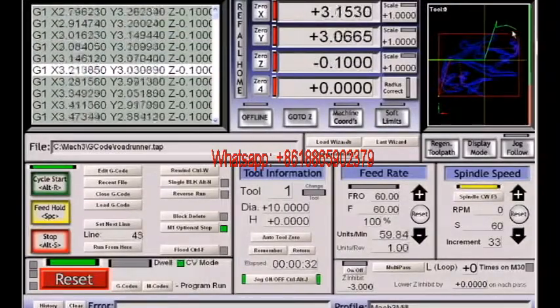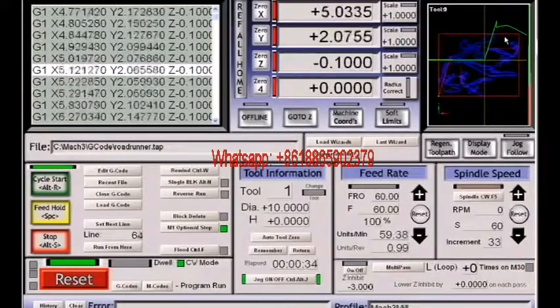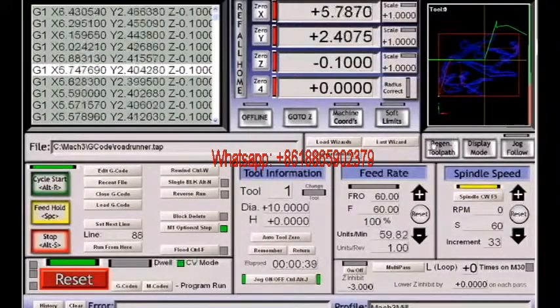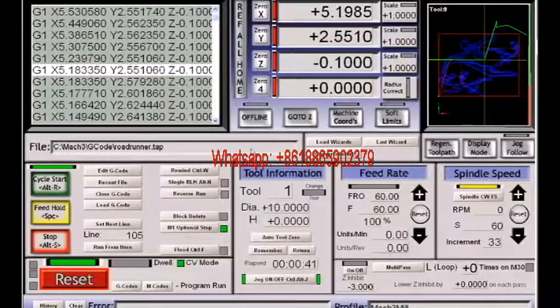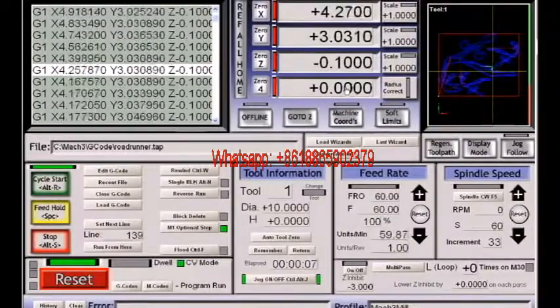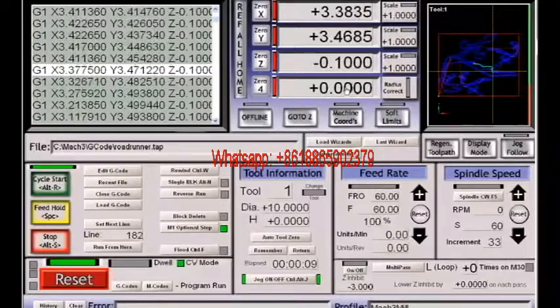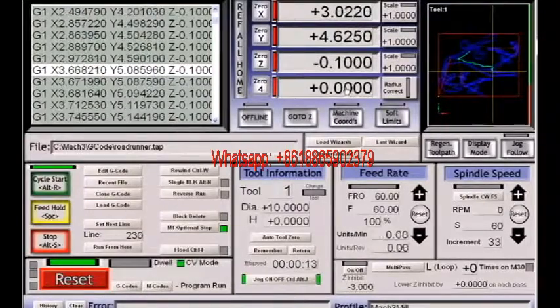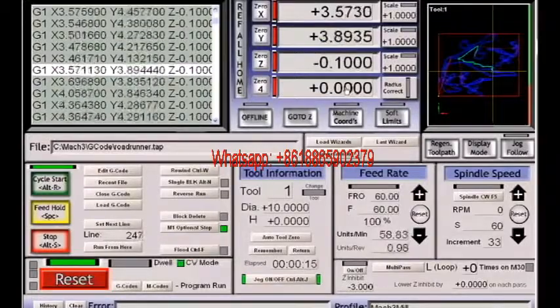Now you notice it's cutting in the wrong place. That's because we did not regen the toolpath after all our playing here and zeroing. So it's important, I'm going to stop this again, to regenerate the toolpath after you've been zeroing. I can now tell the program to start, and again it's not moving because I'm not rotating my MPG. As I rotate my MPG now, the program, as you can see, follows through and cuts only at the speed that I rotate my wheel at.